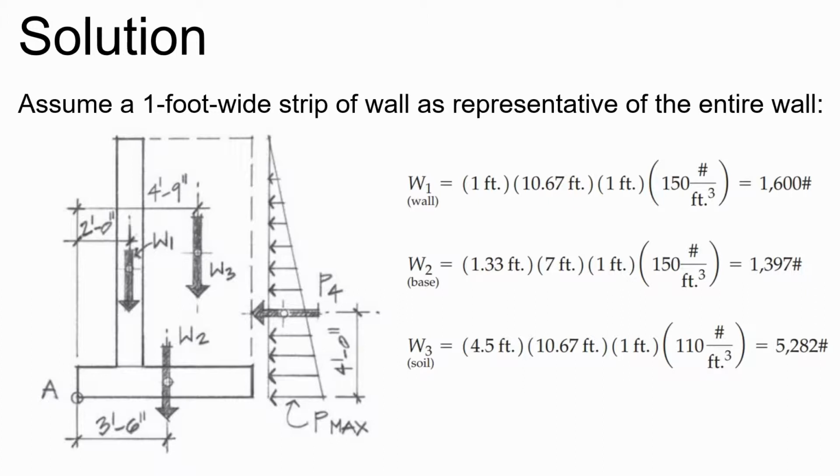The weight of the base is equal to 1.33 feet times 7 feet times 1 foot times 150 pounds per cubic feet, or 1,397 pounds.